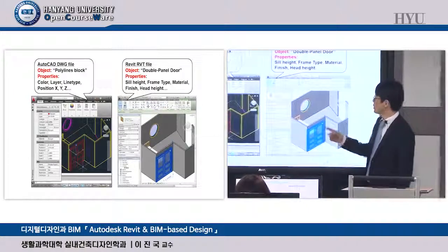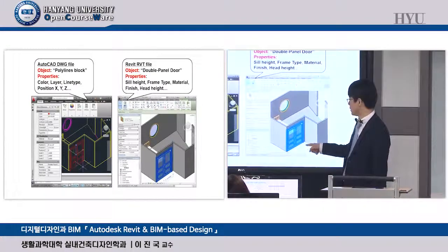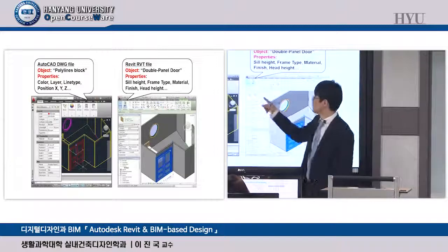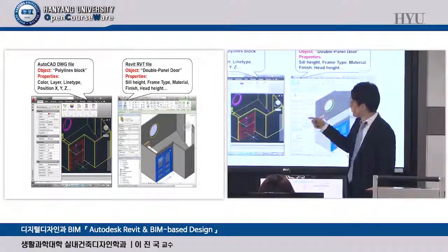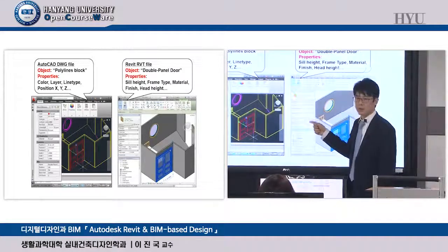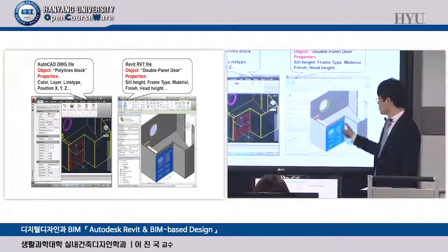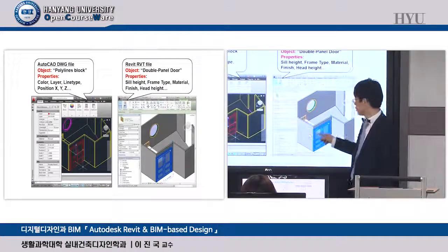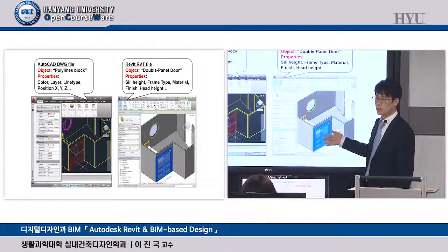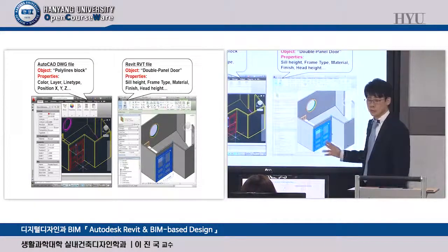But when you export that into Revit and open it in Revit and click this door, this one knows it is a double panel door and associated information. But a bunch of things are missing because the original source of this one was Homestyler, which is a really simplified BIM tool. So you can add more information. You can edit, delete, do something. It's a BIM tool, okay?